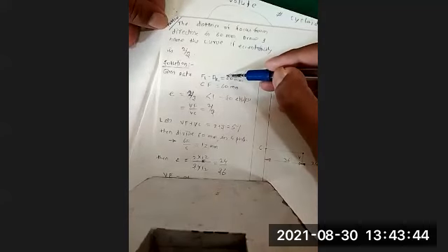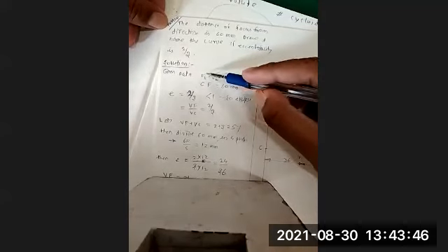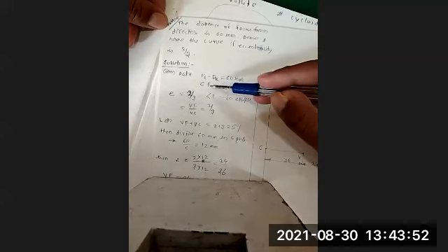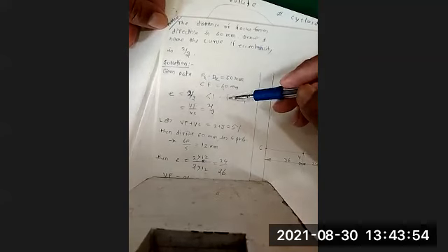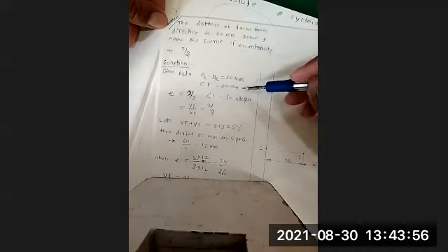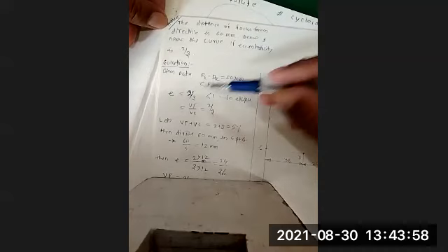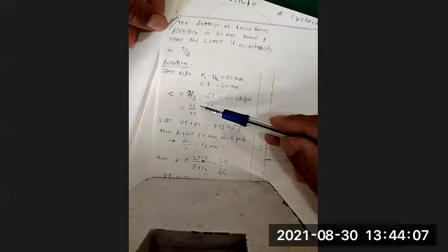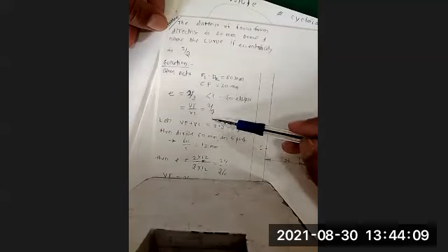So in short, you write down the given data: fixed point to directrix, that distance is 60 millimeter. Means in terms of CF and V, you can say CF is 60. Eccentricity is given 2 by 3. It is less than 1. So the curve is ellipse. So VF by VC is 2 by 3.